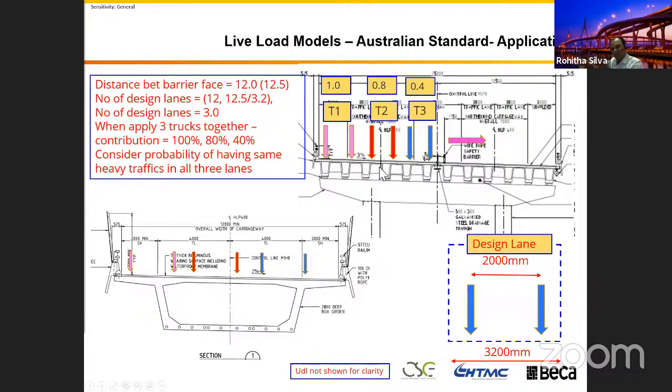If you push your load to the right side, and if you load the other side as well, you create maximum load within your span in the cross beam, right? Because this reaction will come down, right? It will make sense. It will position most of the significant portion of the load in here. Therefore, you produce maximum sagging in your substructure, right?